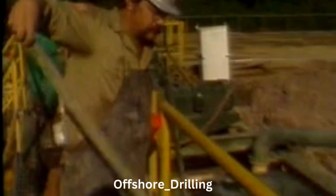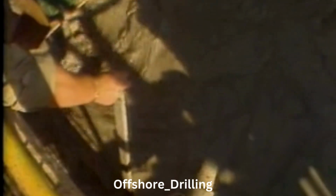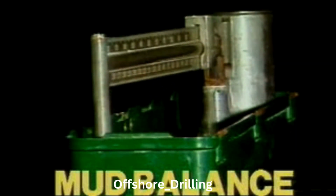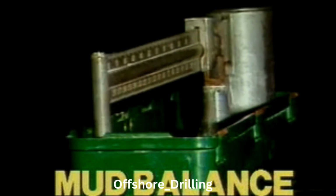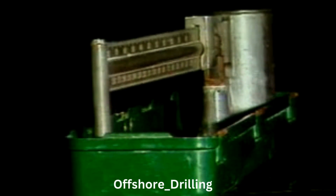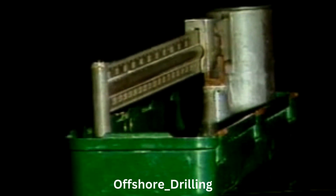Whatever the reason for changes, the mud weight is important, so your tests have to be done regularly and accurately. And both you and the mud engineer will be taking the weights. So naturally, a scale is needed, and you've probably already been introduced to a mud balance of some sort by now. But I'll bet you didn't know that every week or so you should check it for accuracy.